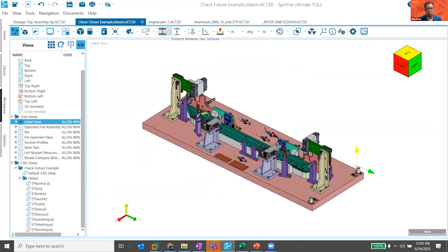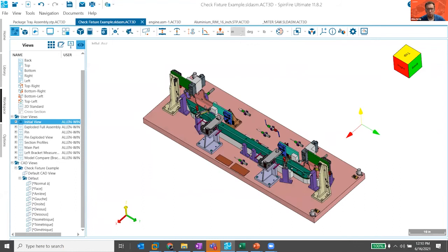the time looking for the specific measurement type that you're trying to get to, you can just use the smart edge, and as you hover over specific areas of that model, it will recognize whether you're hovering over a surface or a straight edge or a curve, and it'll give you a set of measurement types based on what you're hovering over.